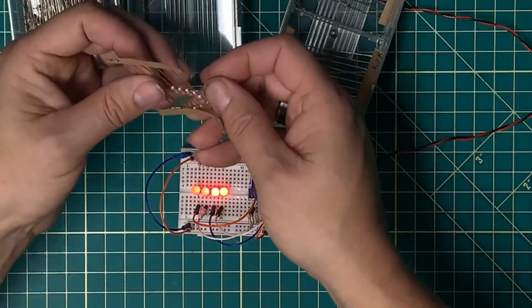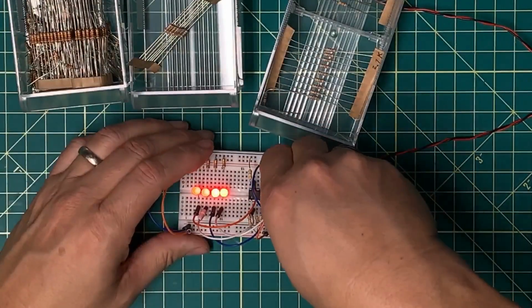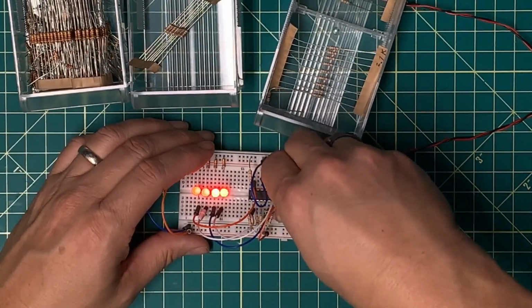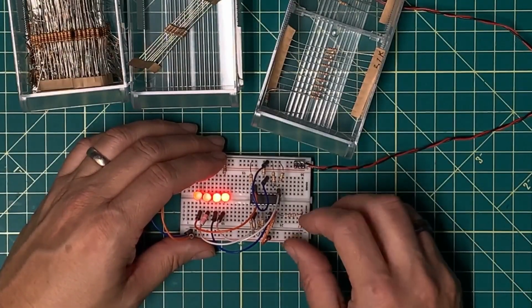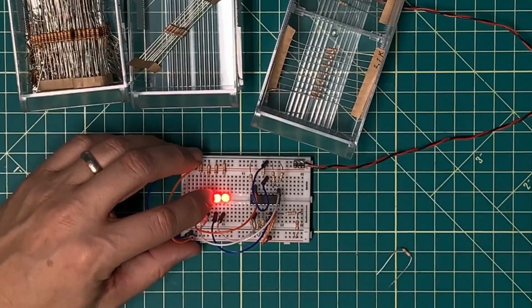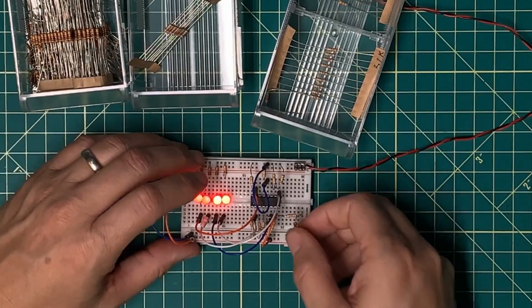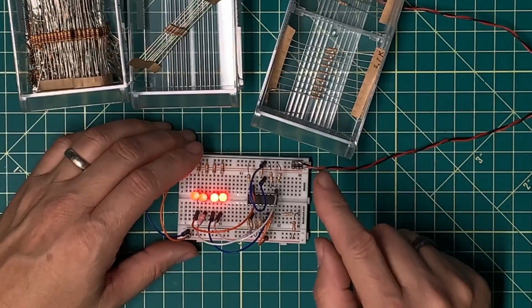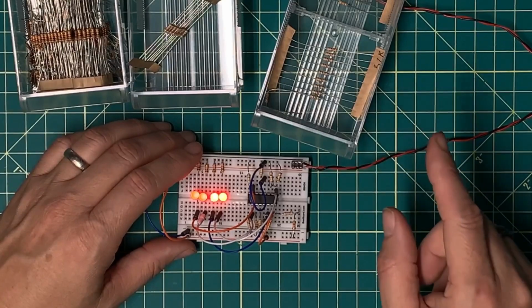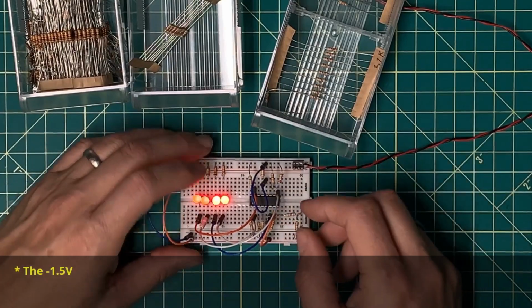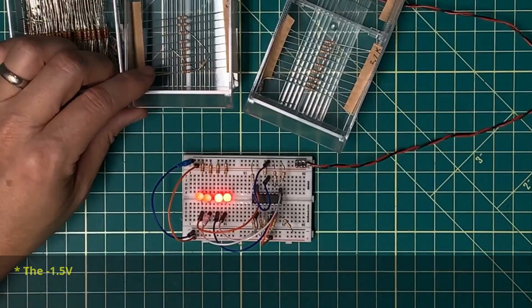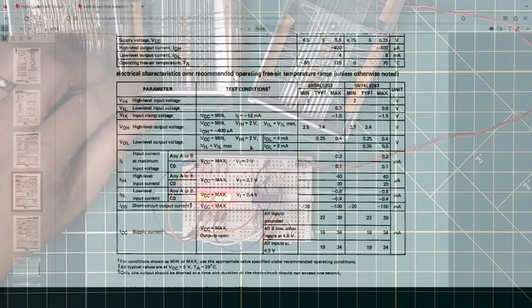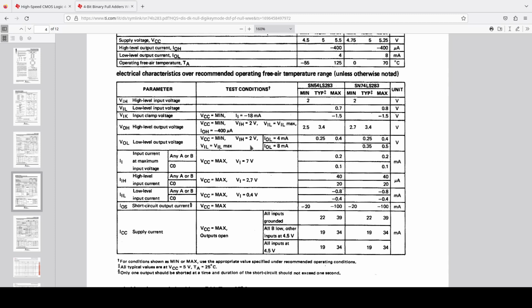Now, for the 2.7 to 3.3K range, I can certainly grab a, let's see here, where is it? A 2K. And then a 1K. So I have a combined resistance of 3K. And the 3K is not pulling that low. So somewhere between 2.7K and 3K is the magic number that's able to overcome that 5 volts, which I found to be very interesting.